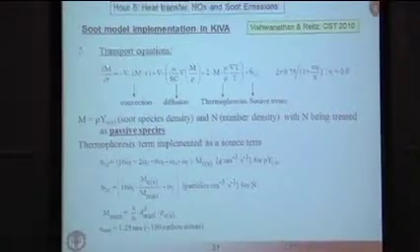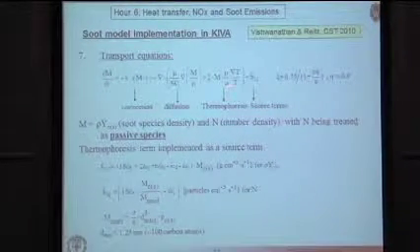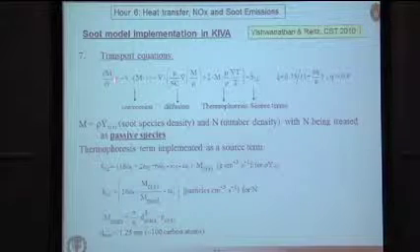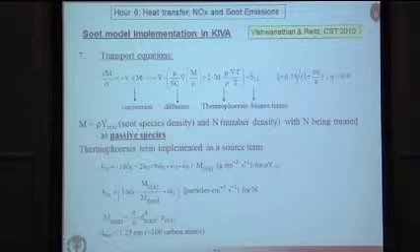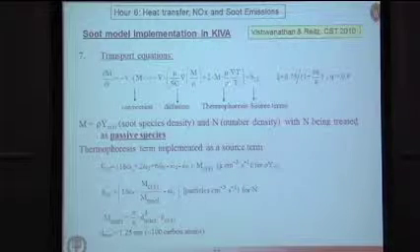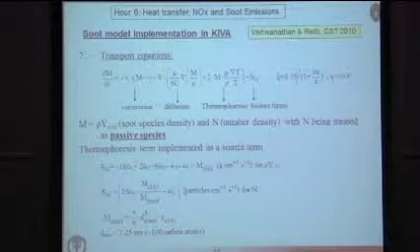Okay, I mentioned those partial differential equations. So here is the transport equation. M here can either be the soot species density or the soot number density. So it's one of those two. So this is two partial differential equations. We can calculate then the rate of change, say, of soot species density due to convection, diffusion, thermophoretic effects, and also source terms.